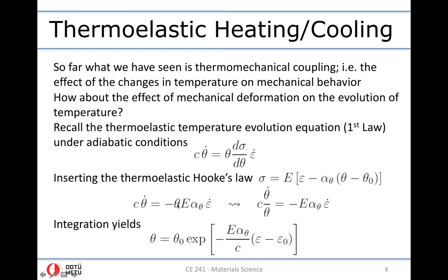And theta is absolute temperature that is always greater than 0. Young's modulus is positive. Thermal expansion coefficient is also positive. That means all these material properties are positive and absolute temperature is positive. Therefore, this equation tells us that the sign of the rate of the temperature is just the opposite of the sign of the rate of the strain. This obviously explains what we observed.